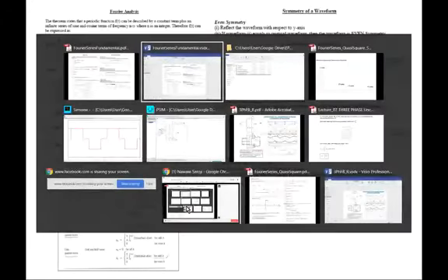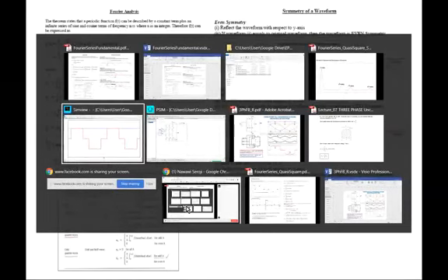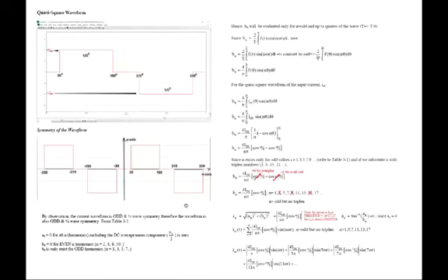Let's move to the quasi-square waveform. If you refer to the input current, it is a quasi-square waveform. We have 30 degrees, then the pulse is 120 degrees, so the next angle here is 150 degrees. There is 60 degrees apart, therefore that will be 210, and a further 120 degree duration, and then we have 330 degrees.